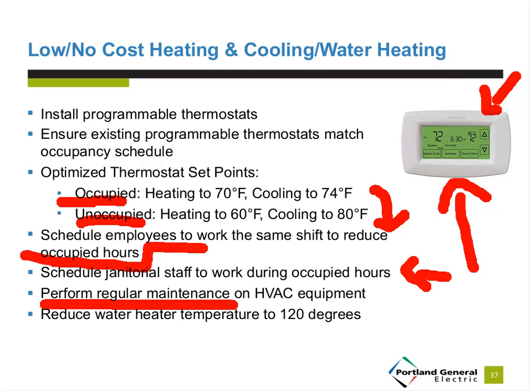Water heaters. Water heaters are generally factory set at 140 degrees. We recommend 120 degrees. With your gas water heaters, it might not have a temperature setting. There are ways that you can figure out how warm the water is coming off the tap, like with a candy thermometer or something like that. Electric water heaters tend to always have the water temperature on the water heater. Just remember that the electric water heater has 2 thermostats for the 2 units, one at the top and one at the bottom. You have 2 plates, you unscrew those, and you can turn it down to 120 degrees.